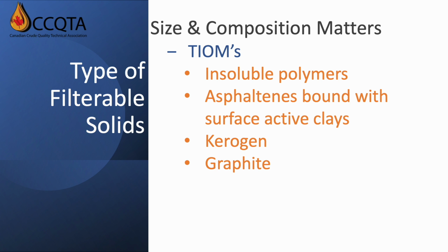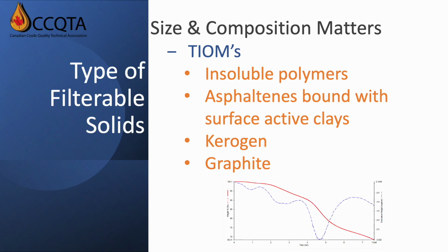When D4807 was initially published in 1988, filtration would reveal deposits composed primarily of inorganic materials. However, over the last 25 years, CCQTA members have consistently also identified TIOMs on their filters. These are often found using thermal gravimetric testing of the filter solids. TIOMs will decompose under high temperatures with and without oxygen present, leaving only inorganic solids behind. Evidence has also been collected through CCQTA projects that TIOMs contribute to equipment fouling and plant operability issues.